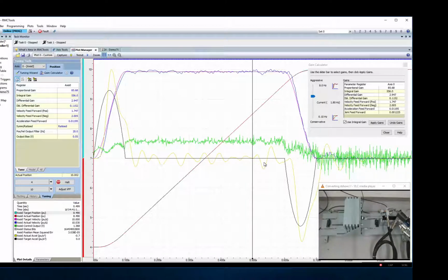So the point of the whole demonstration is using the second derivative gain makes it so that you can control a system very well with a cylinder that has a natural frequency that isn't 4 times the frequency of acceleration. Remember, this is a cylinder with only a natural frequency of 6.4, not 20. So what does that mean to you?